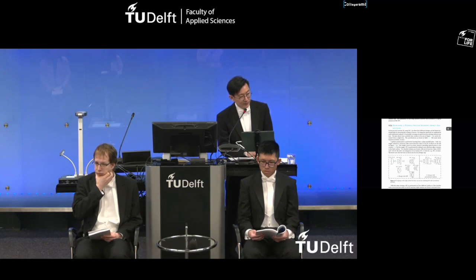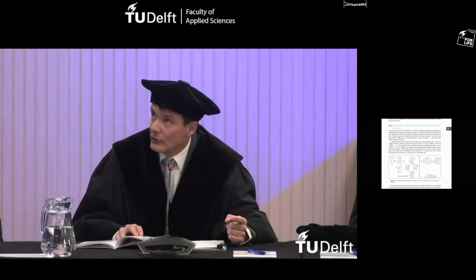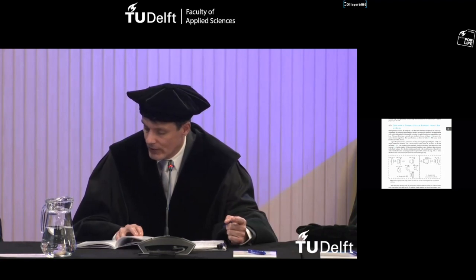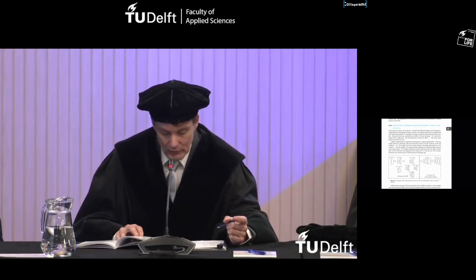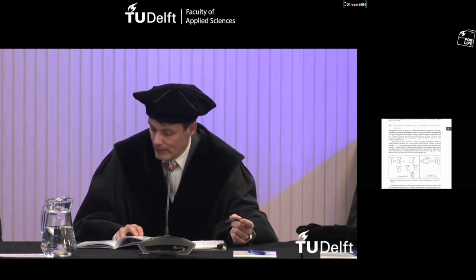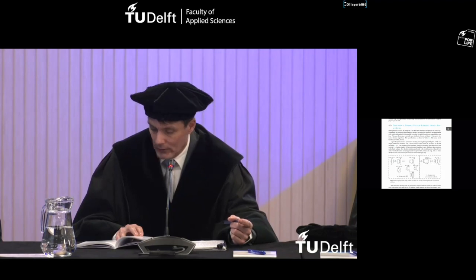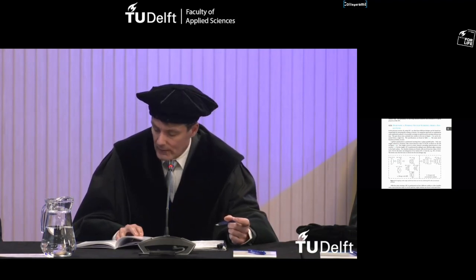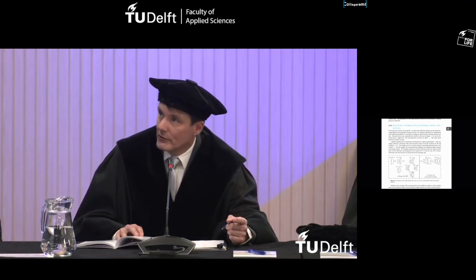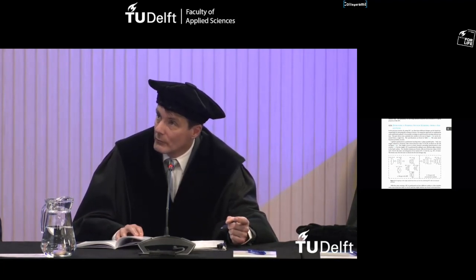Okay. And all these steps are described in the text. So then you say, I add one lens element at the end and do your local optimization with SPC. But what if you would add something at the front? Would you obtain the same result? So that's the one with a merit function of 164.82.